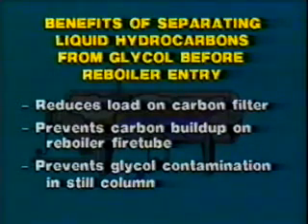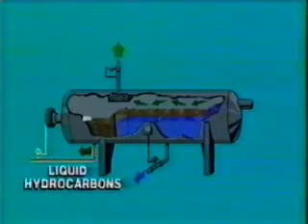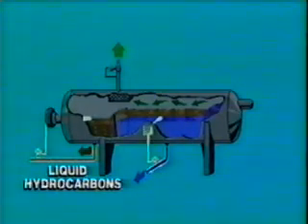Two-level control systems are typically installed on gas condensate glycol separators. The upper system regulates the flow of liquid hydrocarbons discharged from the vessel. The lower system regulates the flow of glycol from the vessel.